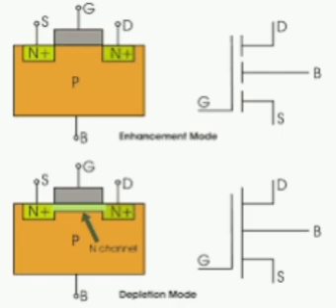The magnitude of photocurrent increases with increasing intensity of light falling at the junction. Current in a photodiode is given by I equals Is plus I0 into (1 minus e power V by eta Vt), where Is means short circuit current for a photodiode, I0 means reverse saturation current, V means voltage applied, and Vt means thermal voltage.